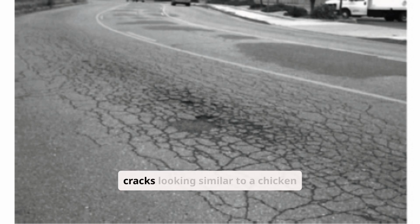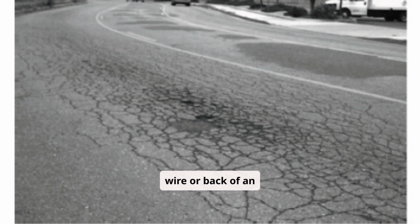A series of interconnected cracks looking similar to a chicken wire or the back of an alligator, as shown in the figure, are defined as alligator cracking. This crack is initiated at the bottom of the asphalt layer due to the damage caused by the developed tensile strain induced by the repeated wheel load. With increase in severity, the cracking propagates to the surface. This is why this crack is very often called bottom-up fatigue crack or simply fatigue crack. However, some agencies use fatigue crack for both bottom-up fatigue and top-down fatigue cracks. Therefore, care should be taken while using the term fatigue crack.